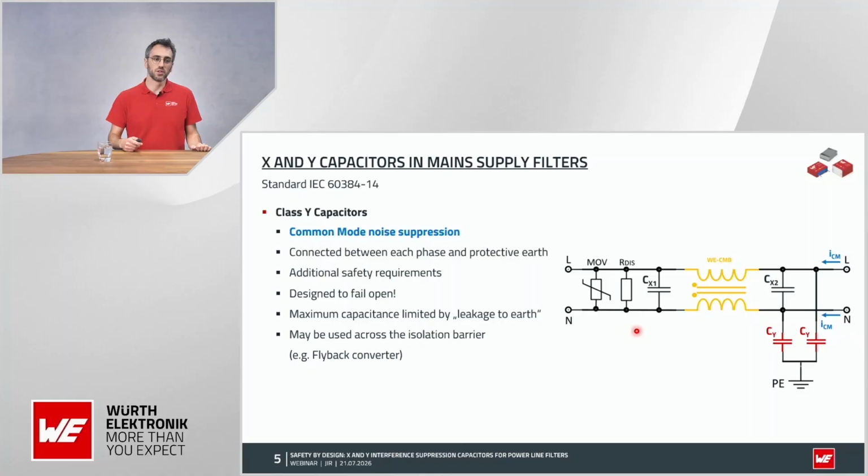Because if they fail short, we could come into the risk of connecting the live phase or live wires to the chassis, and we could put the operator into hazard. So it's very important that the Y capacitors have special safety requirements.